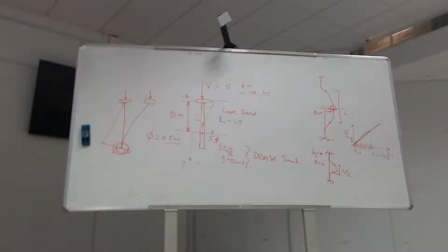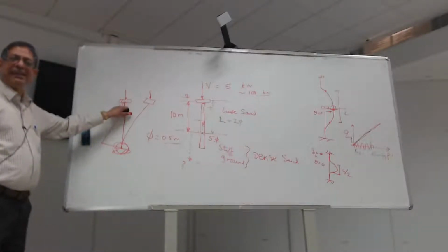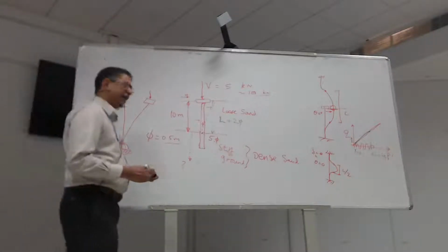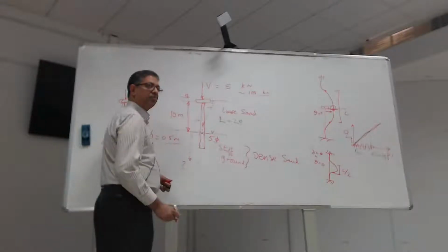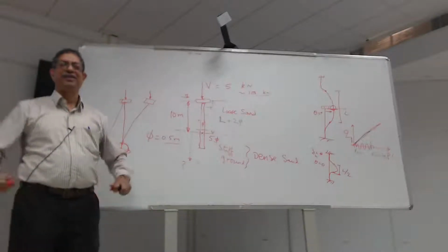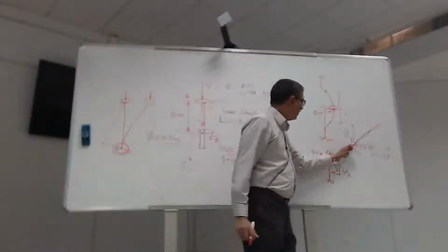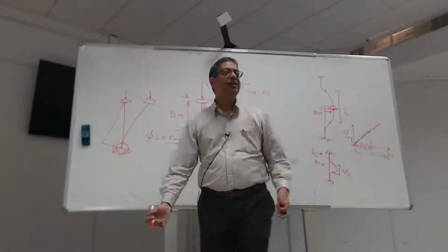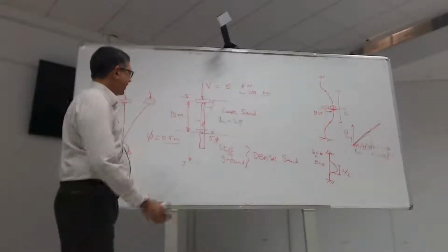Now, so we understand that part of it. Now, why did it buckle up here? It still did that. So our working theory is that the pile wants to do that. It tries every level. First, it wants to form a hinge there. It wants to go that way. The soil gets a snap. I'm at really high confining pressure, so I can go quite high up on this, which means I'll get quite a lot of suction, and you're not going anywhere. And it says, okay, I'll try here.